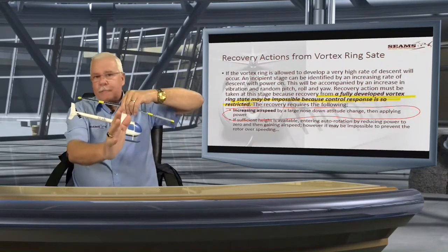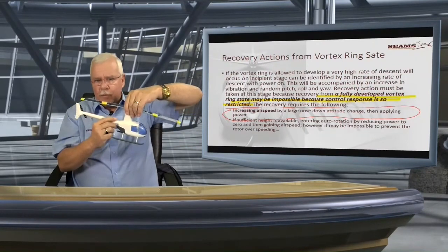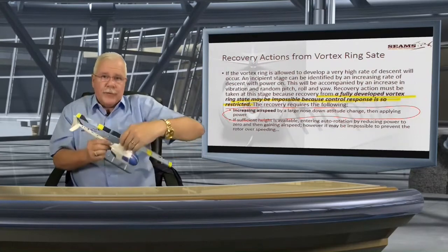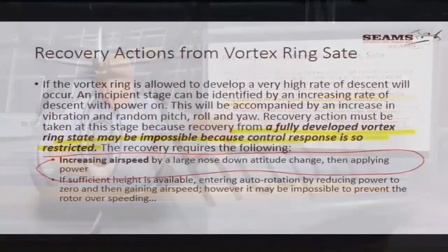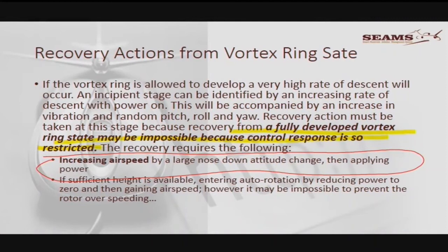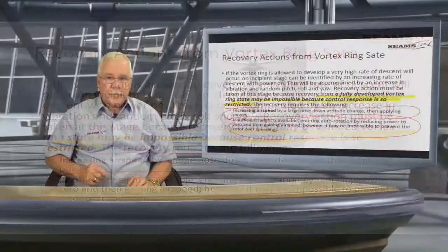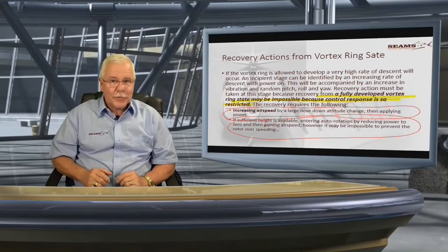If you are sitting with a very strong wind from the side, yeah, of course, you can go into wind. But, you know, I don't want aerodynamically to make this thing not work. Look at it. They say if you have sufficient height, you can enter autorotation. All right, what is sufficient height for autorotation? Come on. You shouldn't enter a fully fledged autorotation below 800 feet.